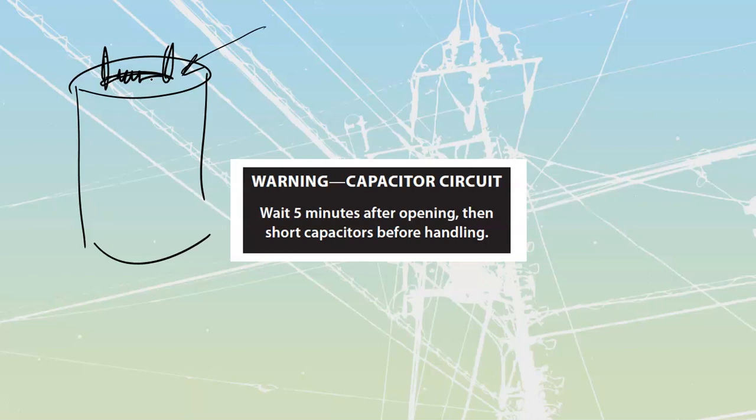And then last of all, never go into a leading power factor. If you oversize your caps and you push all the way into a unity power factor, your terminal voltage will rise on all of your inductive loads and on your transformers, which means that now you're going to have overvoltages throughout your entire plant. Just don't do it. The other main big reason is that BC Hydro on industrial properties monitors power factor. And if you go into a leading power factor, BC Hydro will assess some massive, massive fines against your company.